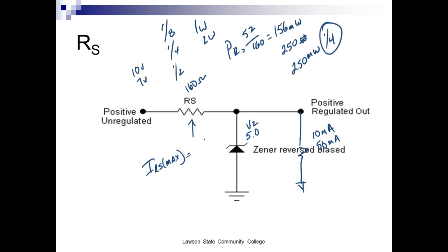How'd you come up with that? Now, what would the maximum current through that Zener ever be? I mean, I'm sorry, through my load resistor. This guy's telling me a lot because the current that flows through the Zener is the difference between what goes through there minus this right here, right? If I can do that, then I know what my Zener current is.